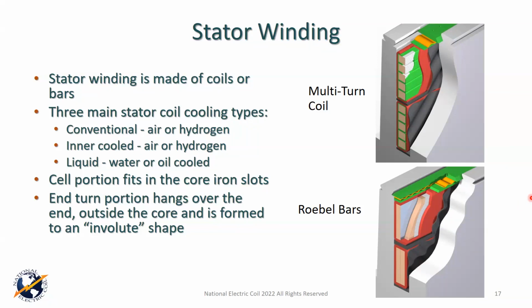Since you mentioned the Inner Corona Protection System, I'll tell you this. There's also an outer corona protection system that's put on the outside of the coil. Most of you, if you've seen coils in the slot, they look kind of a blackish color usually. Some are a very dark green, but most are blackish. That's a semiconductor material. Outside of that, there's what's called the gradient, and it's usually a grayish color. Those two components go together to deal with the surface voltage on the coil.